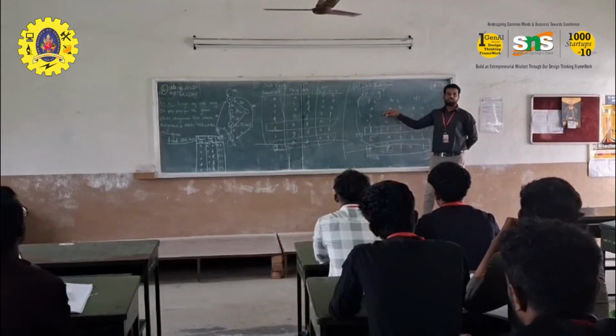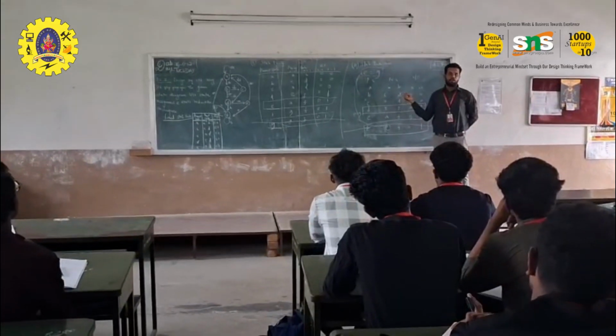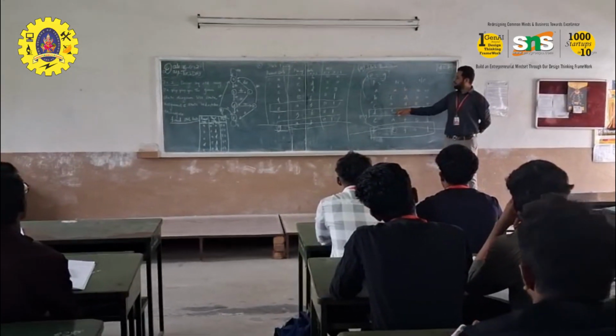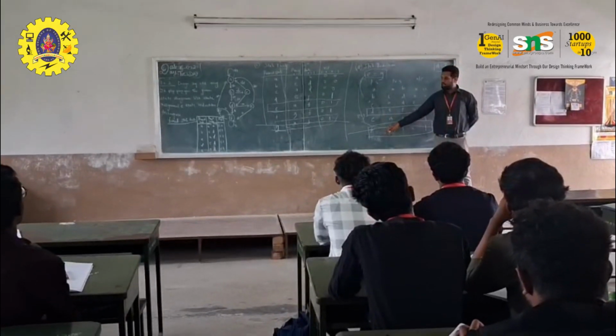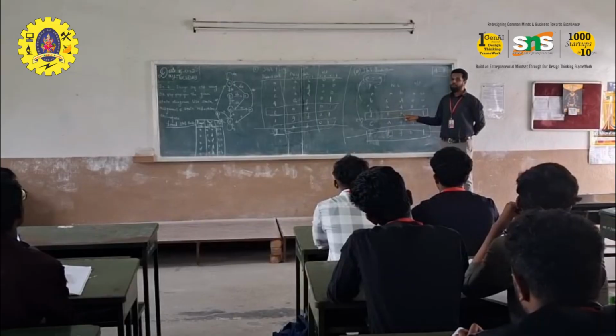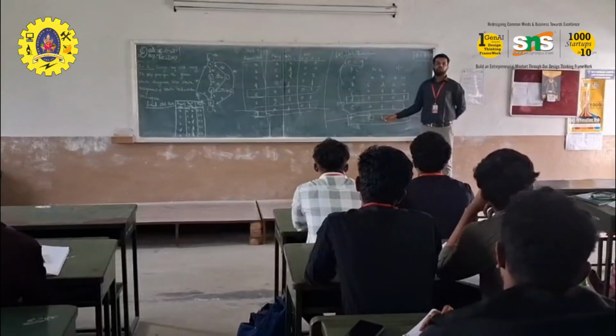After this reduced table, you have to look once again whether any states are repeating their output and next state. Here we can find that the states D and F are repeating. D goes to E and F when the input is 0 and 1. Similarly, F goes to the same E and F when the input is 0 and 1.